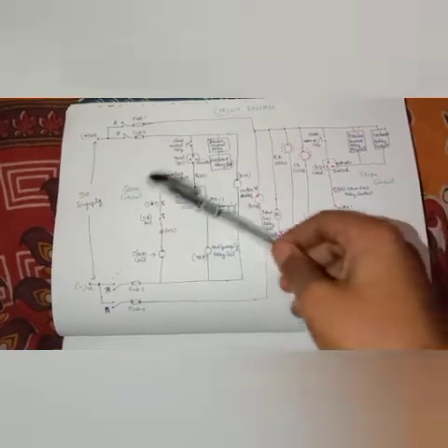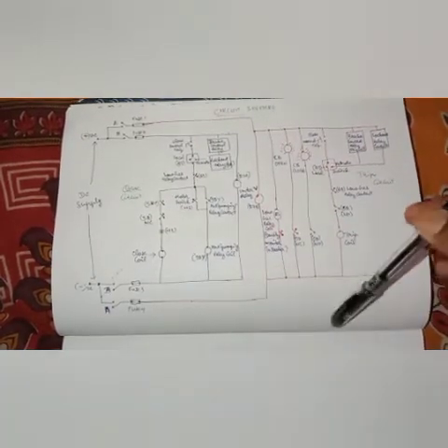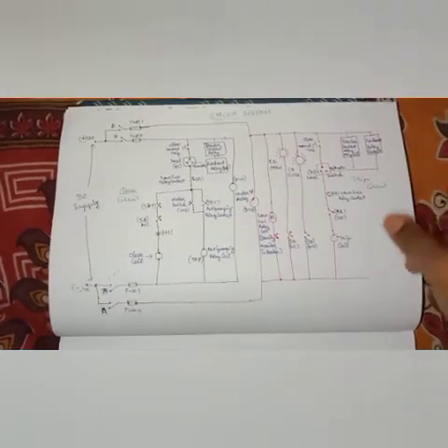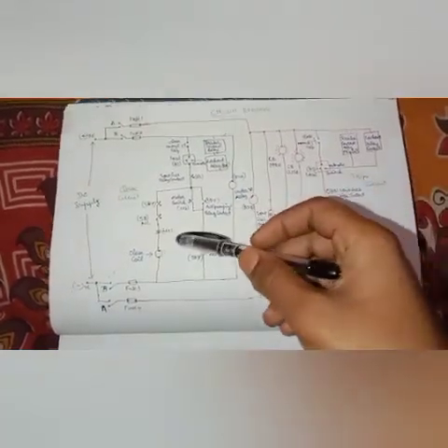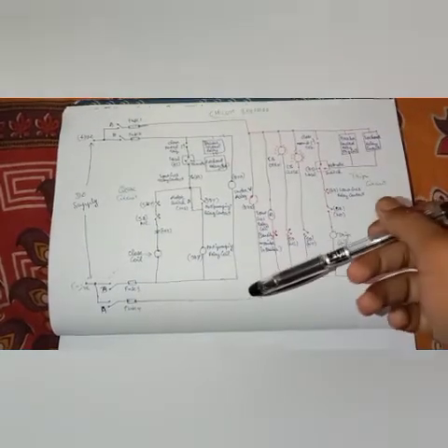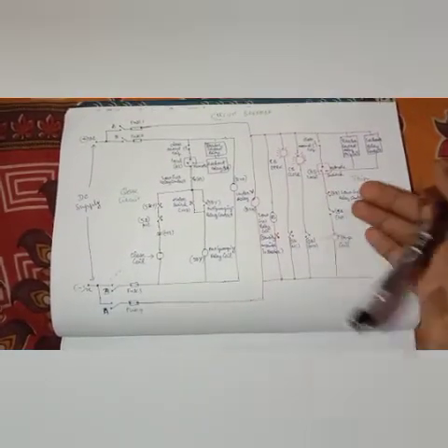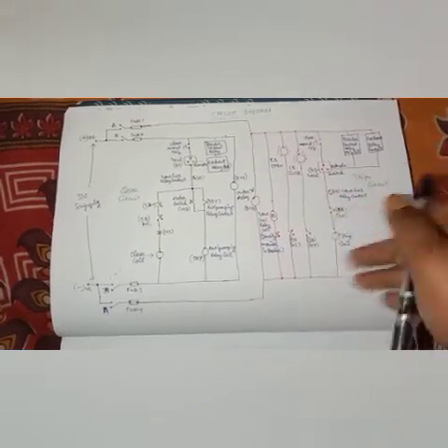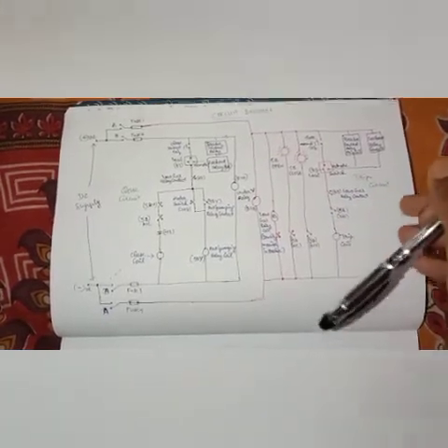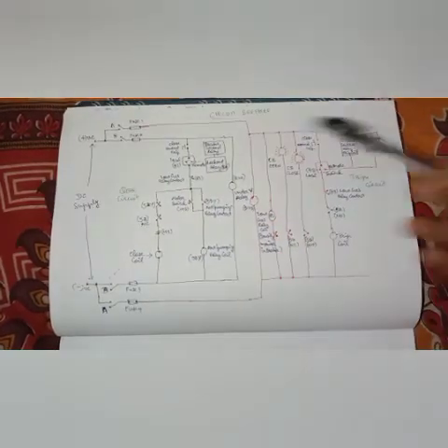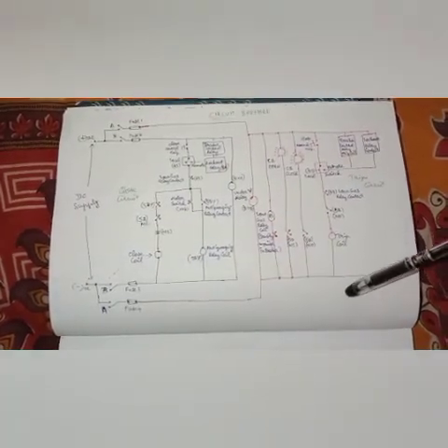And for the breaker we need some AC supplies for heaters and additional auxiliary things. And also for the spring charging we need an AC supply or a DC supply, likewise for that and all. Additionally, the breaker diagram itself we will see in the practical condition. So this is your very basics of your circuit breaker.